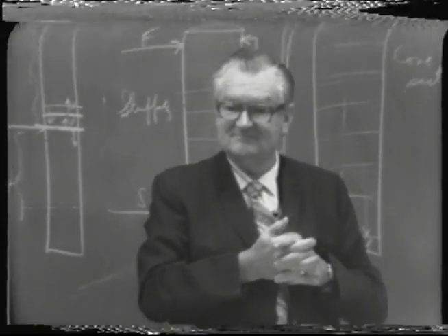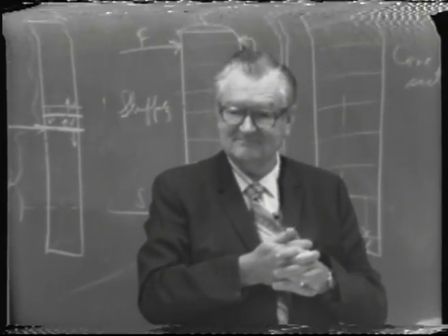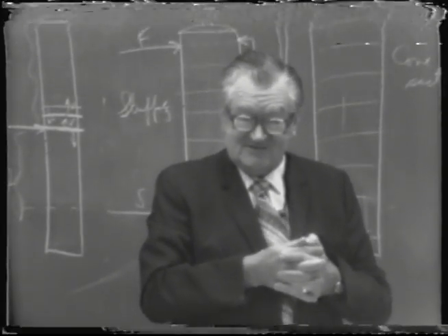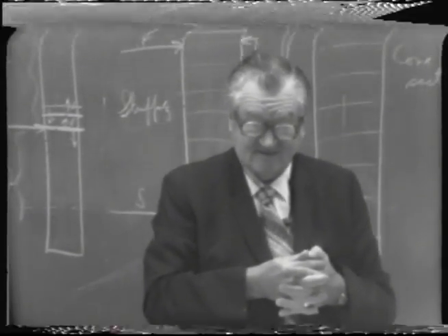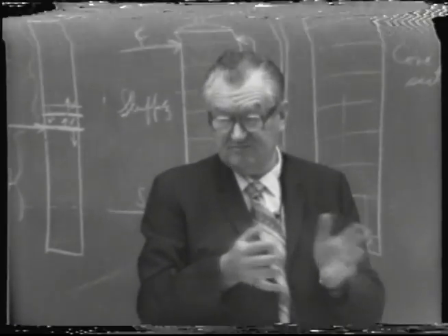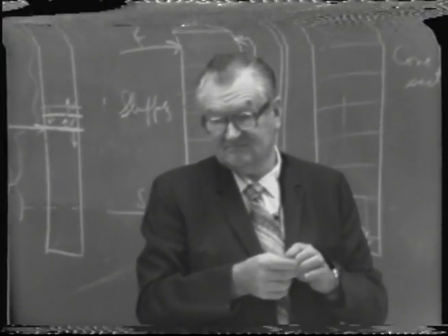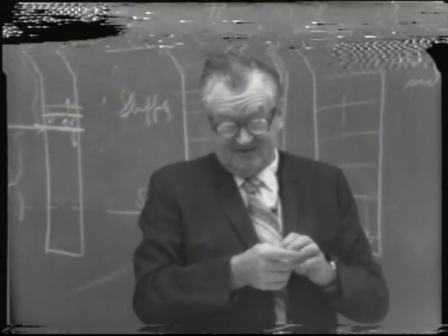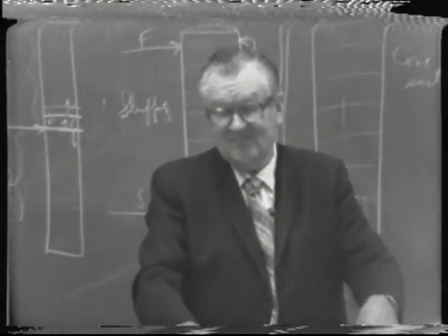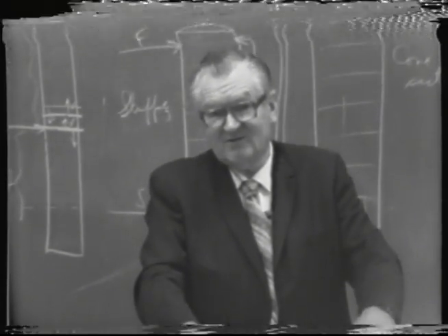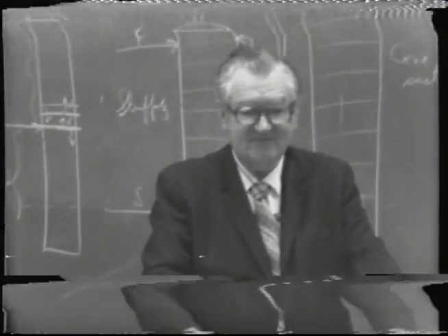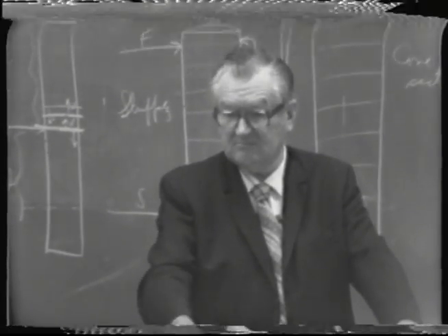How does it remove both high boiling and the low boiling volatile components at the same time? Well, of course, the low boiling components like acetaldehyde and ethyl acetate are more volatile than ethyl alcohol or water in any proportion. That is, they're always more volatile. As I explained before, the components that are the high boilers that have limited solubility in water have volatility greater than 1 only in rather dilute alcohol solutions or water.